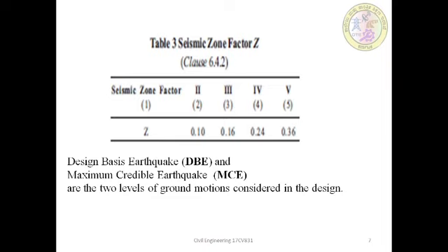That is the maximum horizontal acceleration that can be expected by the structure, and is indicative of the effective zero period level earthquake in this zone. It is referred to as a very high damage risk zone. The regions of zone 5 as per the latest code belong to Kashmir, the western and central Himalayas, north and middle Bihar, northeast India, the Rann of Kutch and the Andaman and Nicobar groups of islands.